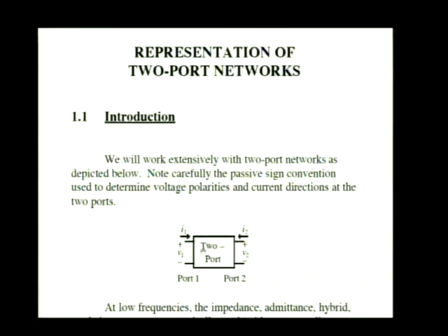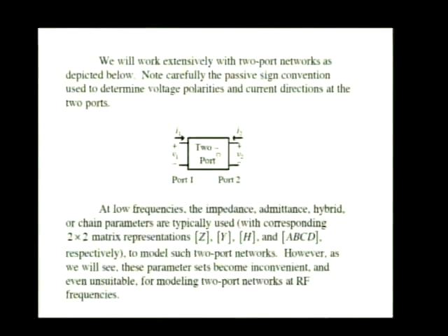You can generalize this two-port circuit to an n-port circuit where n is any number by adding pairs of terminals with voltage V_i defined at each terminal pair and appropriate currents I sub i, which would flow into the positive terminal of the ith port. Well, in any case, our interest is going to be simply with these two-port circuits. We won't need the more generalized concept of an n-port.